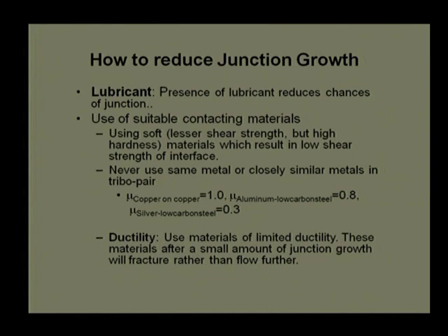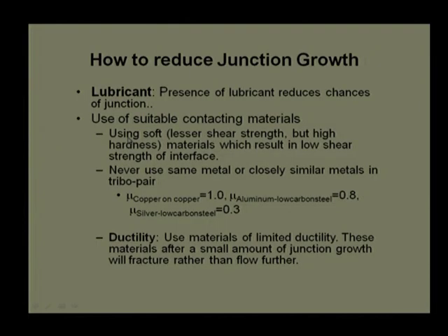It's something like when we play carom board, we use powder lubrication. A similar kind of action, with a loose powder of low shear strength, will work here. And there is a possibility to choose an appropriate material. When you choose a soft material as a third material, it may provide low shear strength, and that may work.